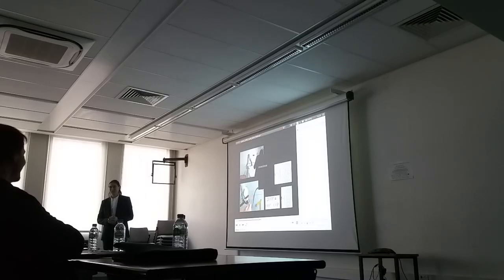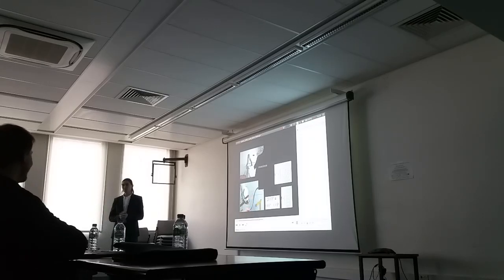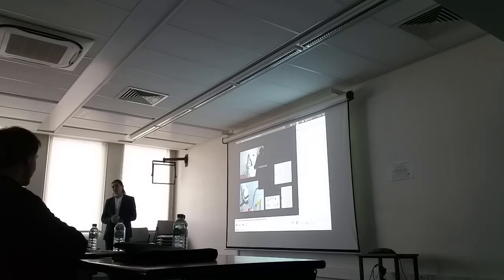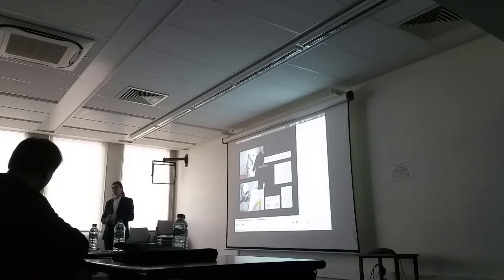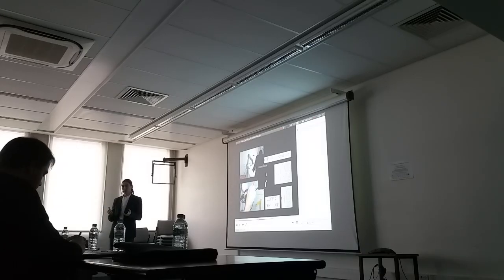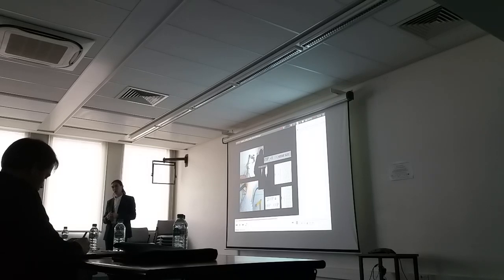Yes. That's the thing. Can you tell me about the damping and stiffness coefficients for the KUKA robot you use? We use the Cartesian impedance controller of the KUKA arm, with the default stiffness and damping parameters.